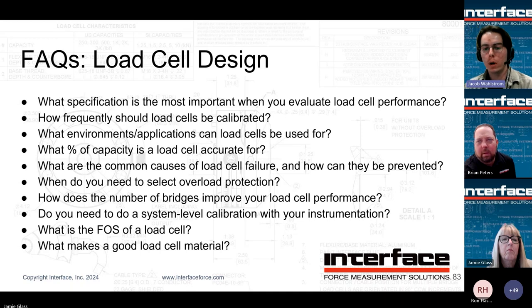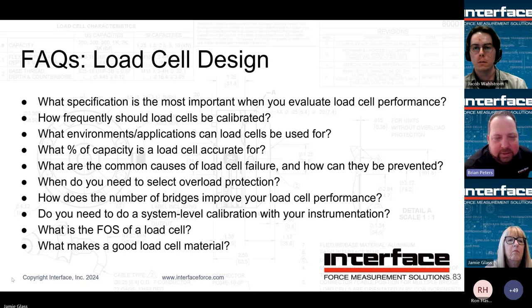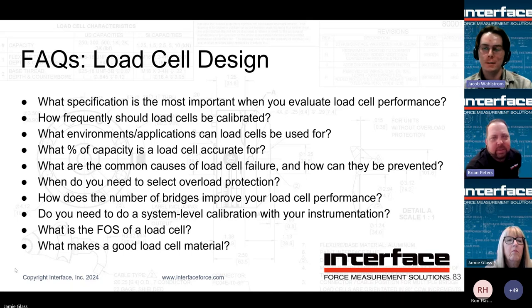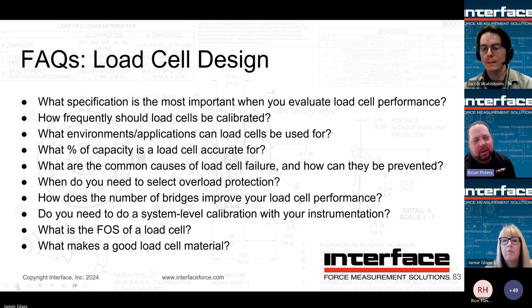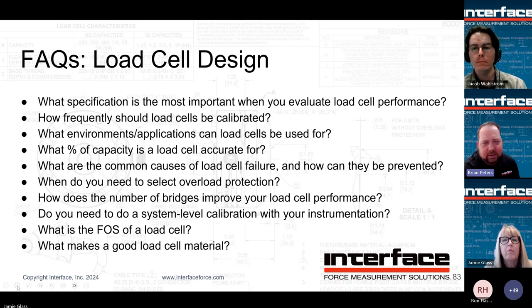Then Brian, what makes a good load cell material? Typical answer: it depends. It depends on the capacity, the application, the environment. As long as it's communicated, we can pick the right choice. But in general, we talked about good load cell materials should have high stiffness, hardness, act like a good spring. That's the key thing. Otherwise, you're going to run into linearity and hysteresis challenges. So, all right,